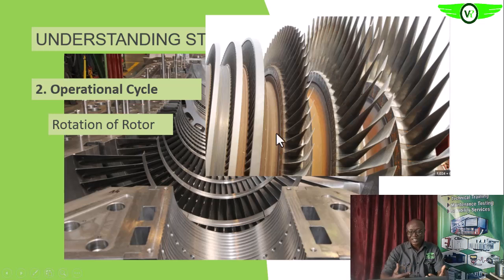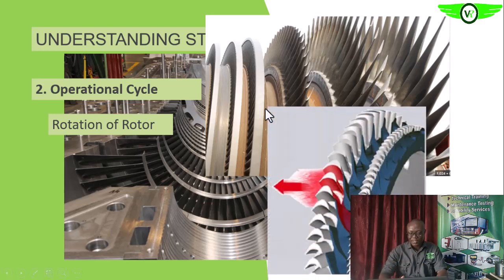So these larger blades are meant to help us extract, as much as possible, whatever is left, the most that can be extracted from that weak, lower energy steam before it is exhausted. So the larger surface area is to help extract more energy from that weak steam.